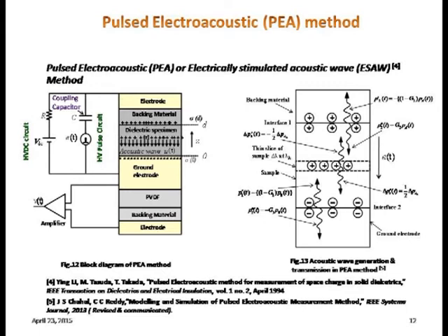The part of the sound wave which reaches this PVDF sensor, the piezoelectric sensor, is converted from an acoustic signal into electrical voltage. That voltage we will tap, amplify and measure. But how to obtain this? When the top electrode is supplied with some DC voltage and the ground electrode is grounded, it means that a certain voltage is applied to this dielectric specimen.